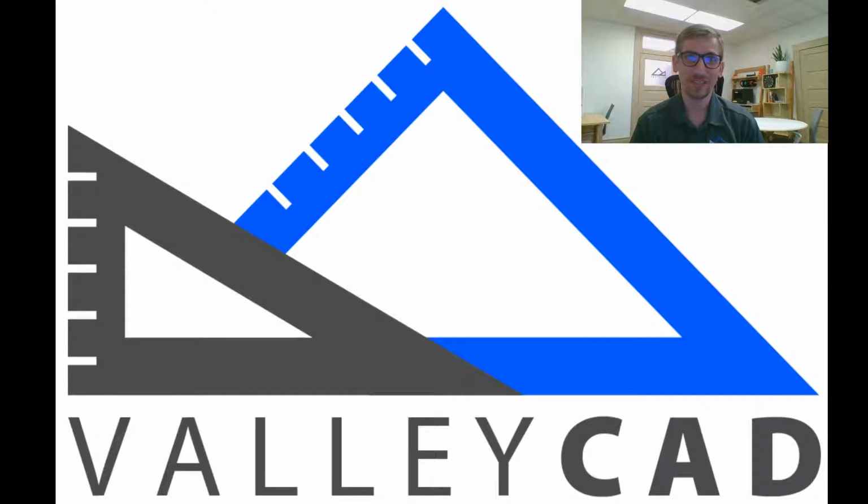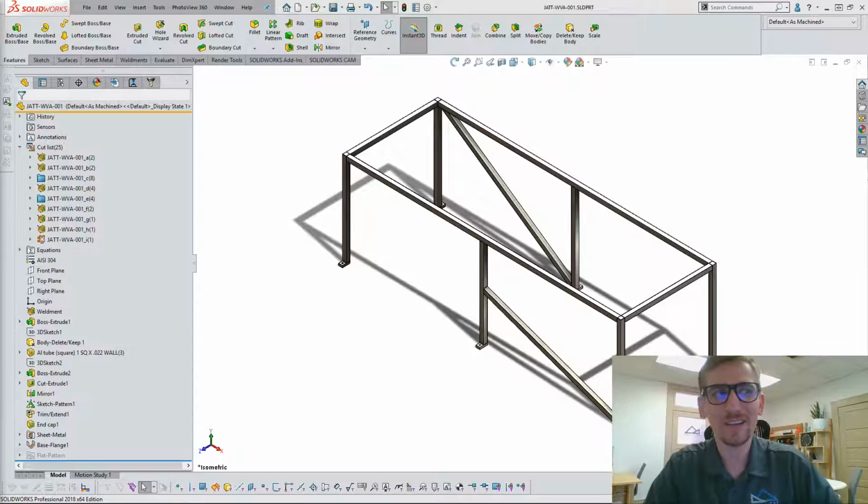I love hearing how other people are utilizing SOLIDWORKS in the sense of, all right, I've got a weldment assembly, and because I call it a weldment assembly, I'm going to make an assembly file in SOLIDWORKS for it. But in reality, weldments should be made in a part file. So I'm going to go into a little detail on why I use weldment part files over an assembly file in SOLIDWORKS. Okay, so let's hop over to it and see what we've got going on.